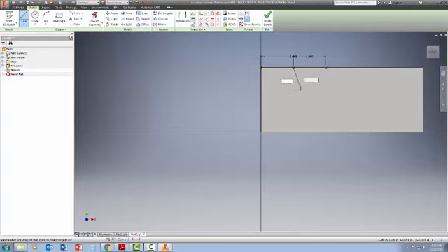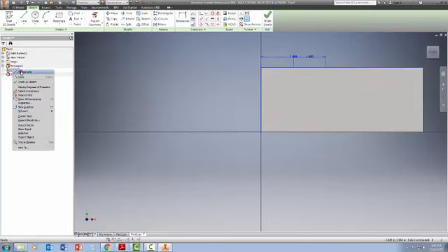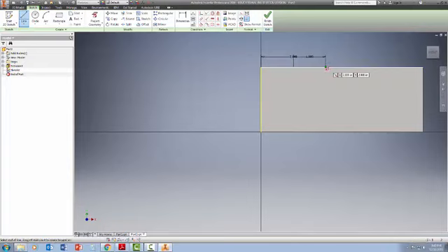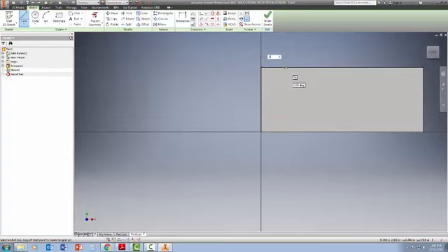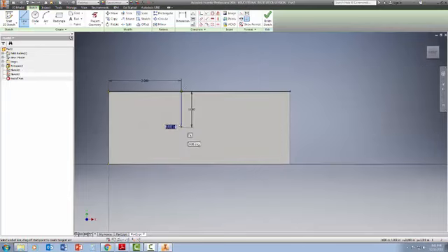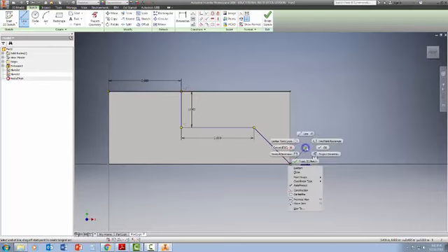Oh no! What happened? I made a mistake. Right click, go to Cancel. Go back to Sketch, just right click on the sketch, repeat line. You can then bring this line down, or I'm just going to right click and hit Cancel. You can always hit the back arrow. Okay, so line, setting at the corner, it turns green. I click, bring it over, how far? 2 inches. Enter. I bring it down, how far? 1 inch. 90 degrees, yep. Over 2 inches. Enter. And then we're going to come down here to the corner and just right click, click on OK.